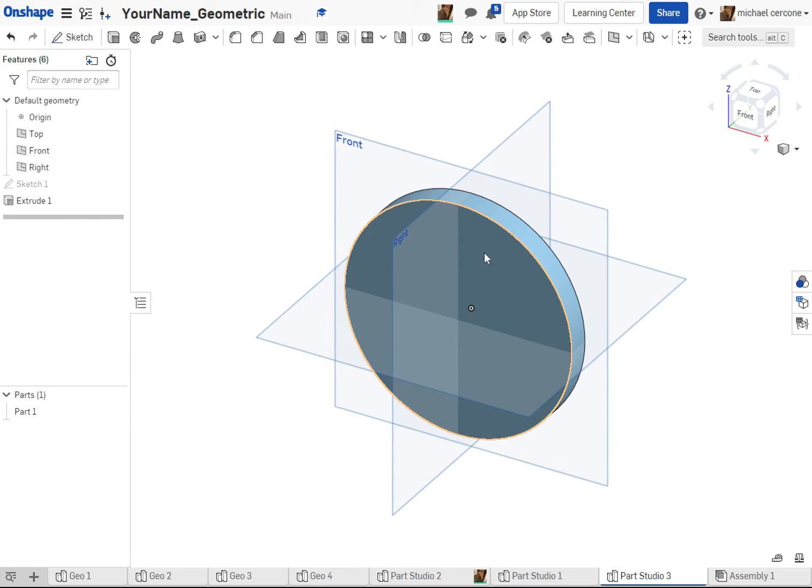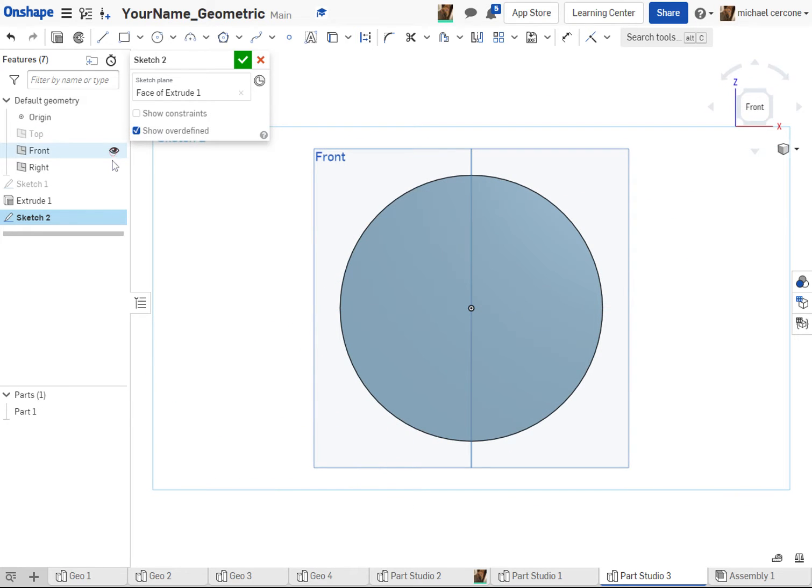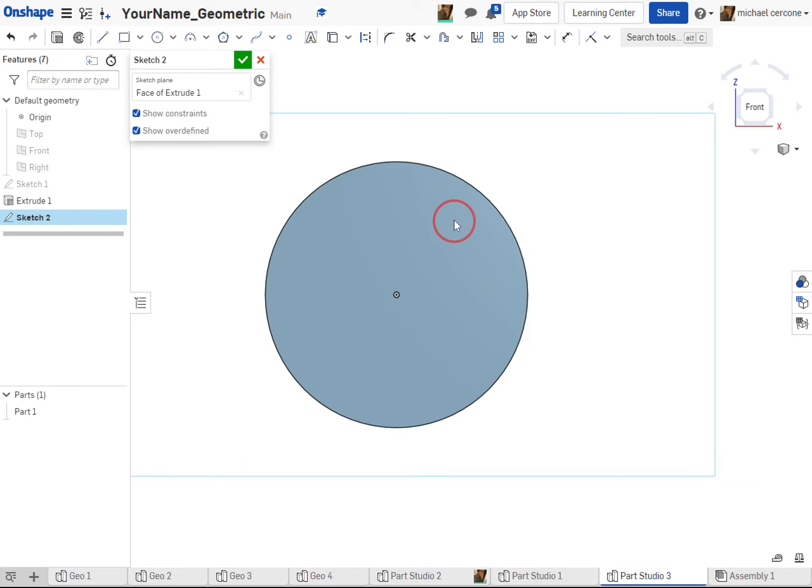All right, now I'm going to design everything independently, starting with the 3 equally spaced slots. I'm going to start with the one on the top quadrant. So I'll start my sketch here and go normal to. Make sure you turn on your constraints. I will tell you there's going to be a lot of additional geometry in some of these sketches that you won't have as part of the feature.